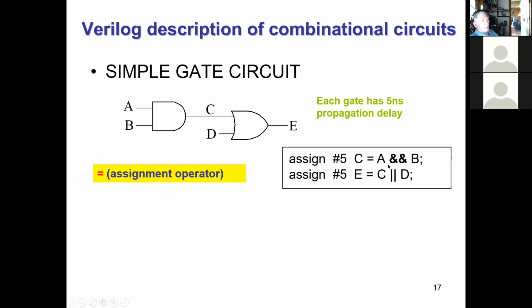So you know from C, that's the logical AND. But because we're assuming these are bit variables, since there's no other comment to the contrary, if these are single bits, the logical ANDing and the bitwise ANDing are exactly the same. But if they're vectors, if they're more than one bit, then logical ANDing and bitwise ANDing are not the same. So you do have to pay attention to this.